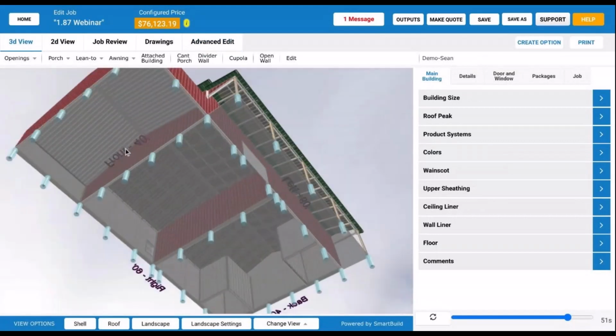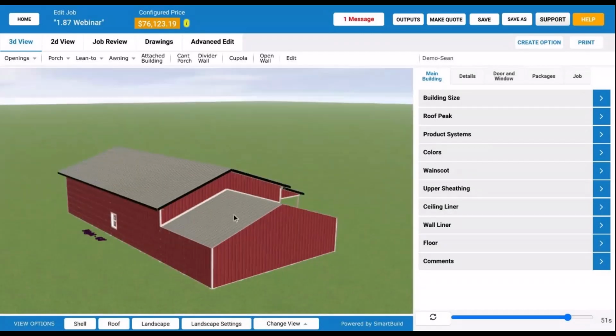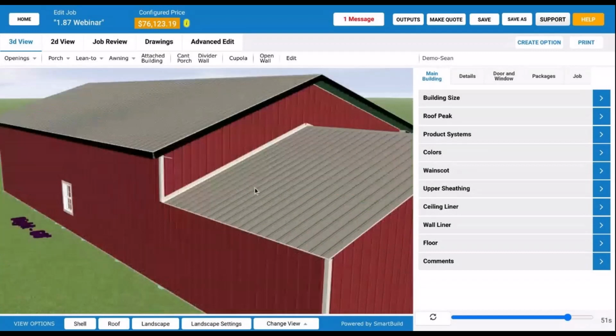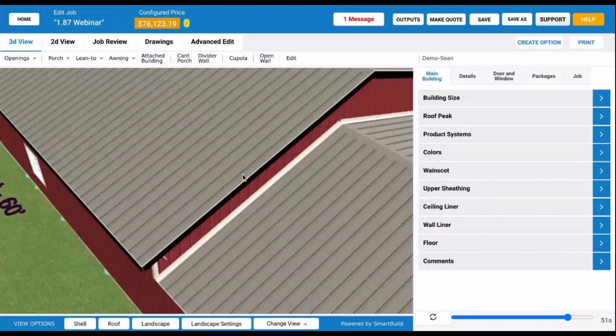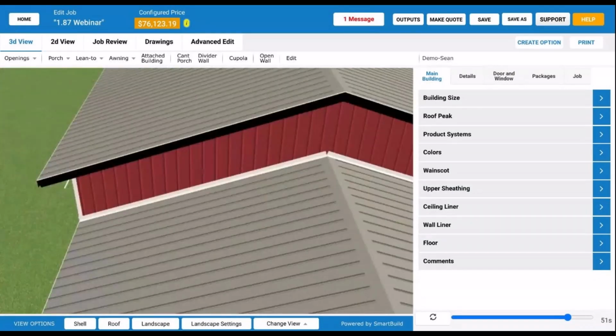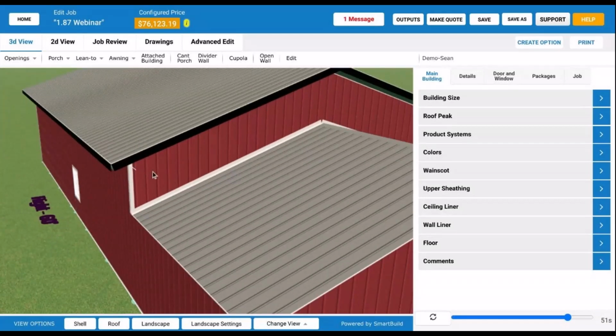So I typically offset the ceiling height by 1/8 of an inch or something like that, but then it also still gives you roof corners, the things you don't need, but it does split the ceiling. Yeah, I've tried that too. It gives you the soffit, it gives you all the trims. Yeah, not ideal. So that's definitely something we want to fix. So yeah, if this roof is the same height here, it'll combine these two roofs, and then you lose control.